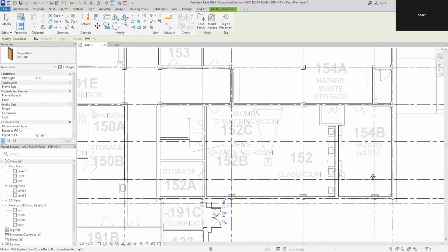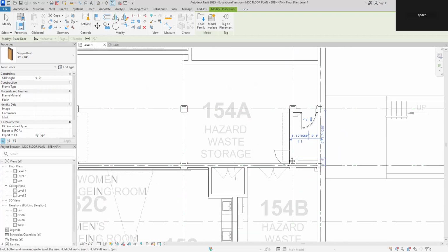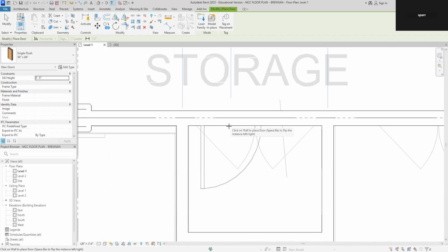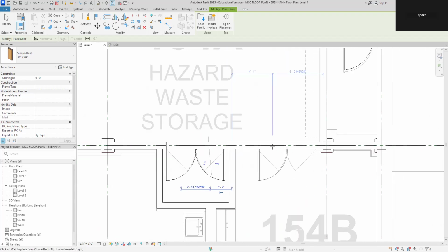So they go in, and remember what I said last week, don't worry about the doors. The actual walls will make their own opening for the doors. It does a whole lot better than you ever could. So don't ever feel like you've got to make a space for the doors to go in. Like we're going to put them over here now too. So there, we're going to do this, and we're going to go ahead and drop that there. Now at that point, this is how these doors go in.